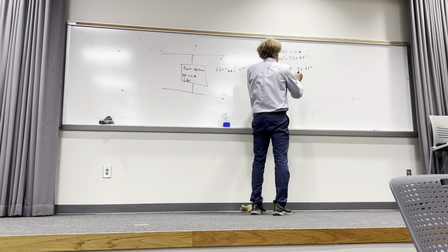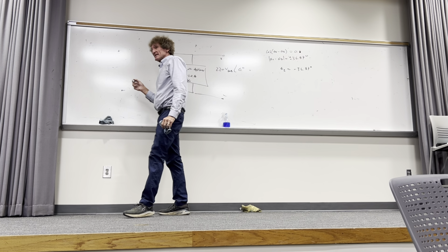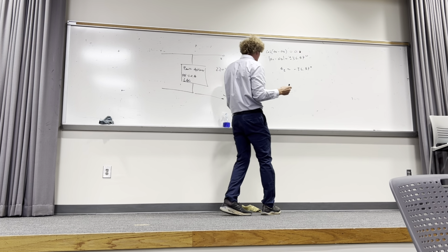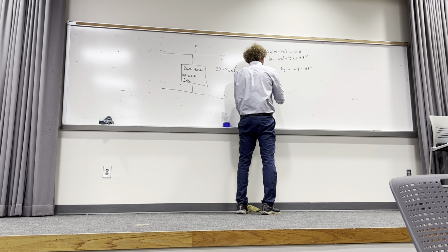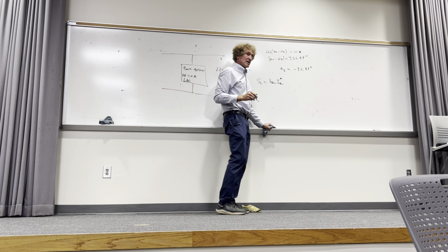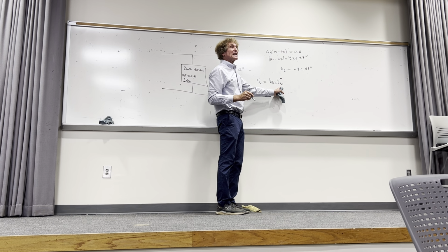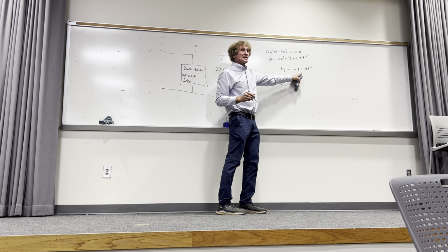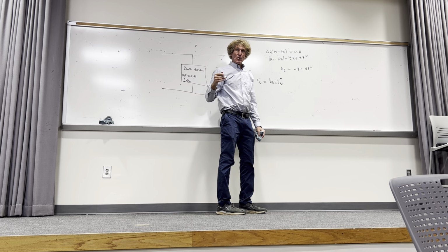Anyway, this is going to be negative. All right? So that means this current is negative, correct? Now here's what it also means. Now we'll look at the complex power. I know it's VRMS times IRMS conjugated, right? The voltage is at 0 degrees. The current here, if the current has an angle that's negative, when it's conjugated, it would be positive. How many see that? So now, take a moment and convince yourself.